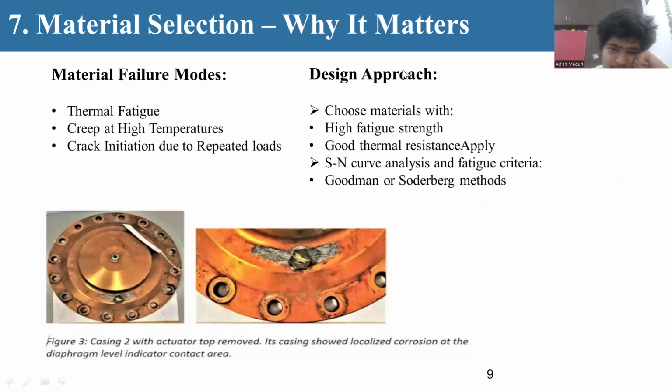And the design approach for this is to use materials with high fatigue strength and thermal resistance, and apply S-N curve analysis and fatigue criteria. Goodman or Soderberg's methods need to be used.